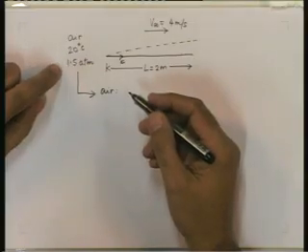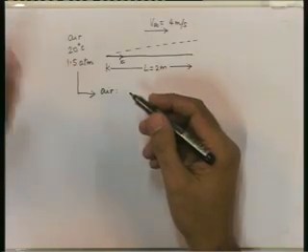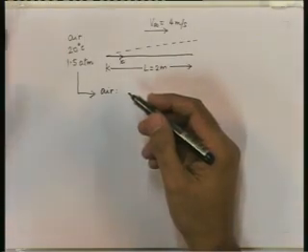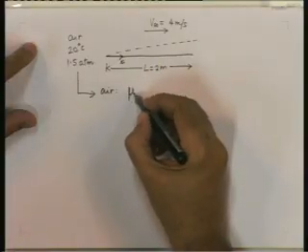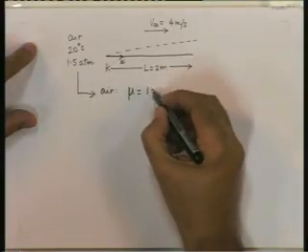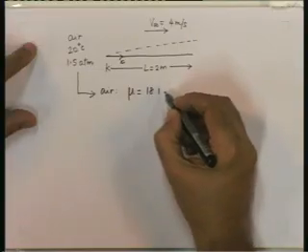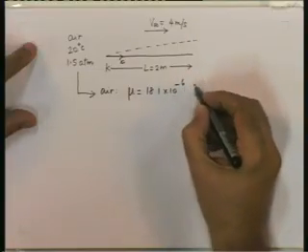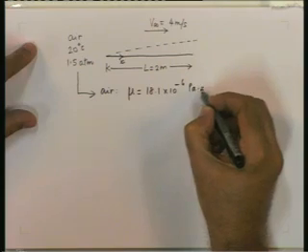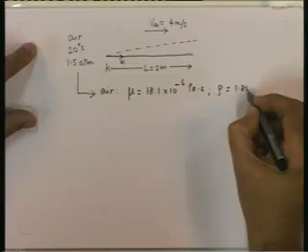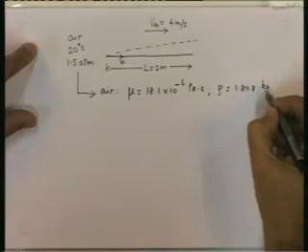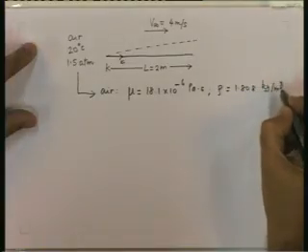So you have to note that the density will increase as the pressure increases, but the dynamic viscosity is essentially independent of pressure. So you get mu equal to 18.1 into 10 raised to minus 6 Pascal second, and the density is 1.808 kg per meter cube.